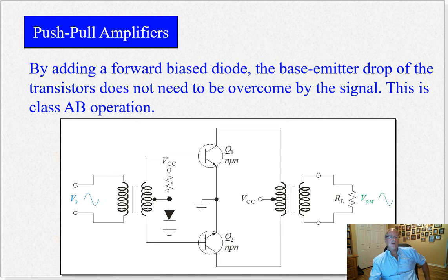Now, the other important thing about this circuit is that all transistors aren't created equal, even if they're the same part number, all right? So this could be a 3904, this could be a 3904 or whatever, and that could be a 1N914 diode. Well, these 3 diodes, they all have maybe 0.7 volts, but maybe not. Maybe one's 0.69, maybe one's 0.71. So they're all different. So typically when you have a circuit like this, you use matched components.